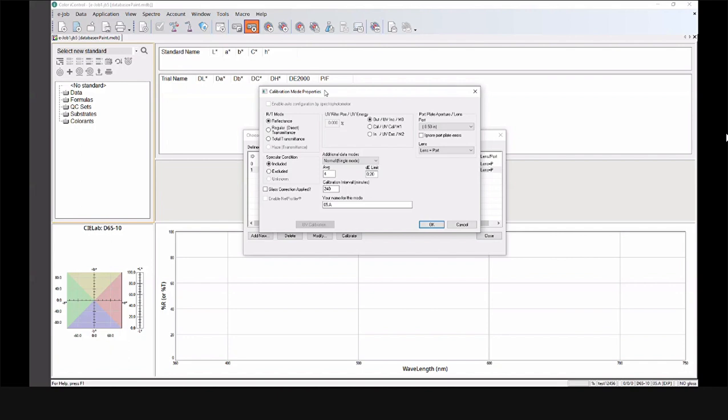For regular transmittance, if there is a specific recommendation from the buyer or customer, or we are doing anything related to dyes or liquid or clear samples, then we should go for regular transmittance. If we are doing anything which is not clear and has a higher particle size, then we should go with total transmittance.